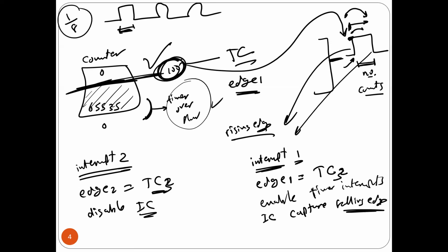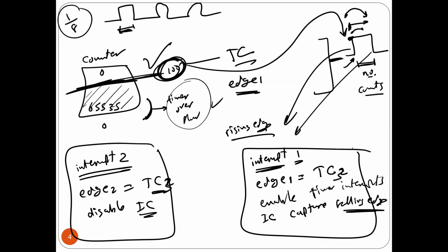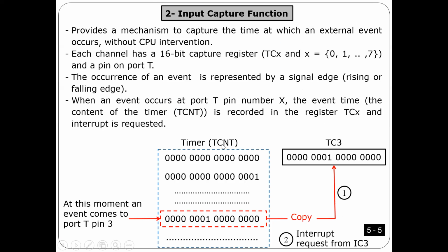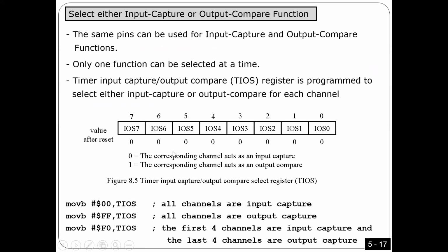Anyway, is that okay now? Okay, now, this is very interesting. So I'm going to write the program. I'm going to use 3 interrupts. I'm going to use 2 interrupts for input capture. This one also input capture. Now, also for the timer overflows. In the timer overflow interrupt, guys, I'm going to increment a variable, we call it overflow, right? So I'm going to have a memory location called overflow because I want to count how many overflows. Is that okay? Again, once you have H1, H2, and overflow, you can do the calculation. Anyway, this is just a very high level description. I'm going to give you the details right now in this program.